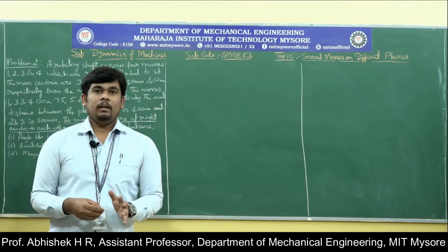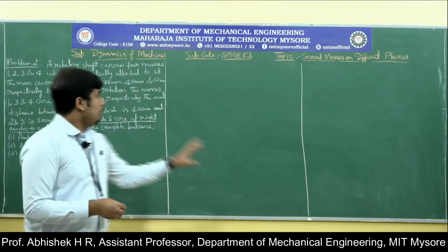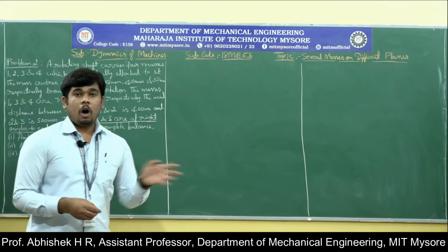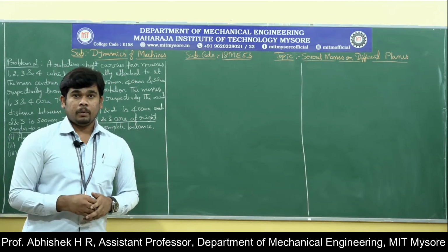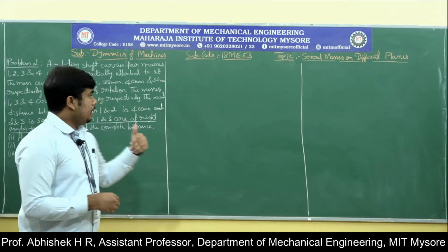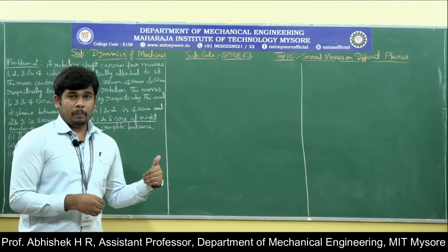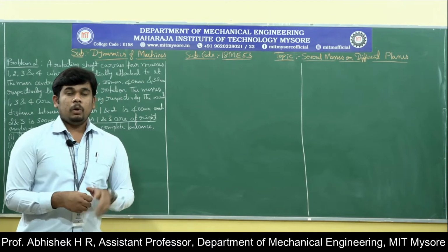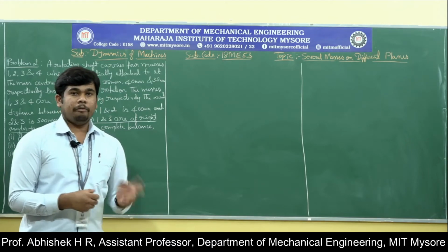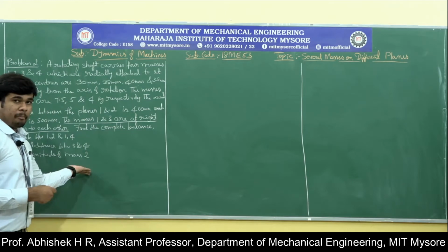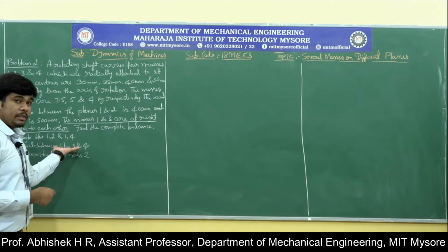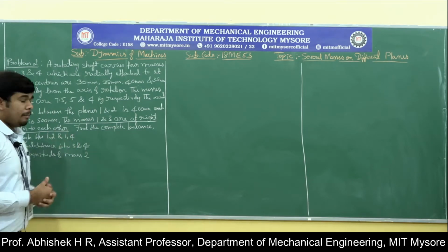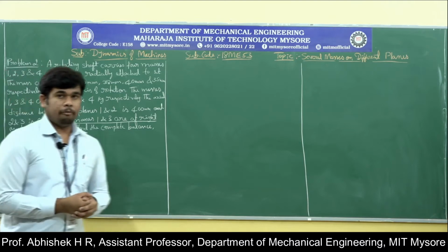We have only the planes 1, 2, 3 and 4, not any other balancing planes. That means in all 4 planes of the system something is disturbing. To balance that we need to find the magnitude of mass 2, the axial distance between 3 and 4, and the angles between 1 and 2 and between 3 and 4.